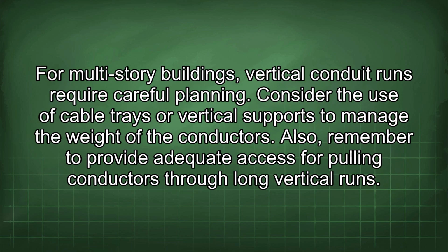For multi-story buildings, vertical conduit runs require careful planning. Consider the use of cable trays or vertical supports to manage the weight of the conductors.